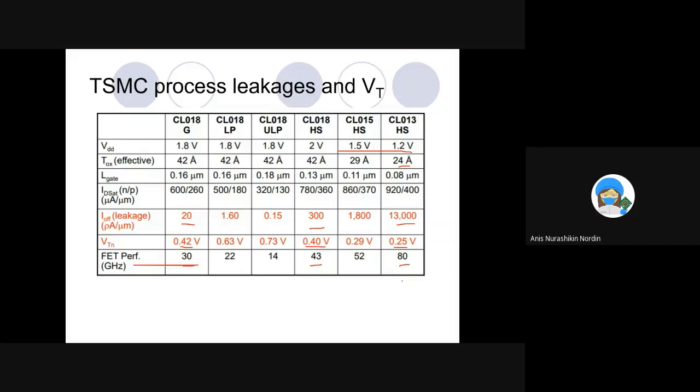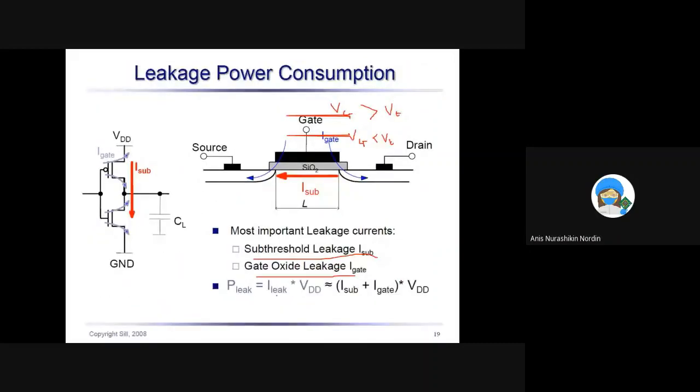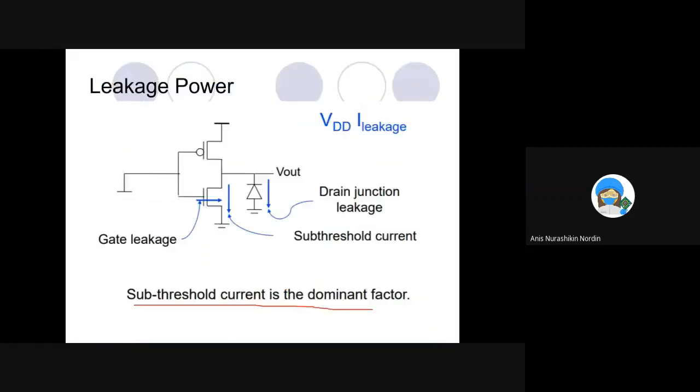Madam, what is the effect when the leakage current is so high, like 30,000 compared to 20? Is it going to increase the power consumption, or is there any glitch in the chip? It will increase the power. There might also be glitches, because with subthreshold current the transistor is more often on when it is not supposed to be on, right? Because the leakage is due to this. So you will have less reliability of your chip.